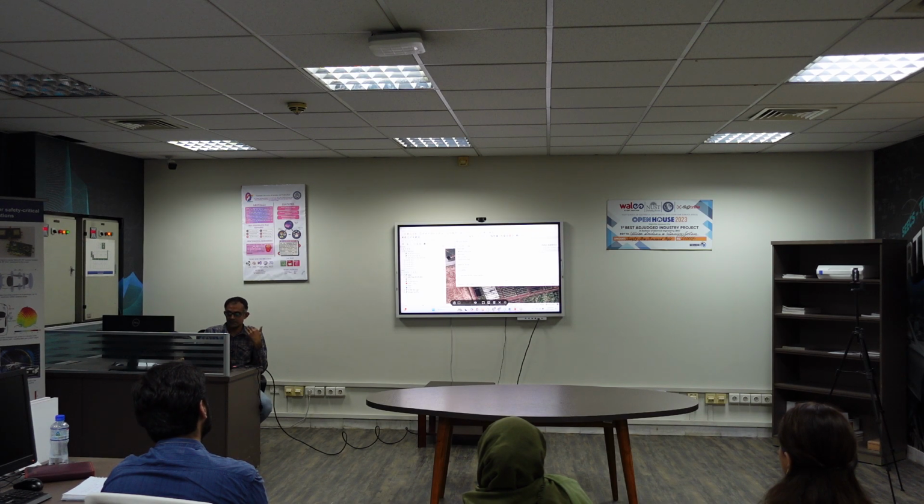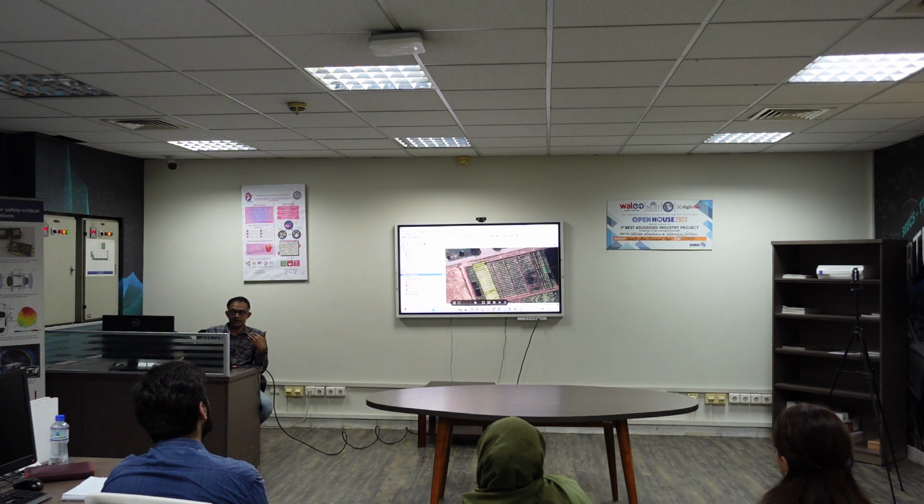And the statistics that it can calculate are numerous. It can count all the pixels, it can sum all the pixels, it can generate the mean of all the pixels, or it can generate the standard deviation, or whatever things are here. Let's just generate the mean. Let's see how it goes. Now it has generated another vector layer, which basically contains the mean of individual plots.